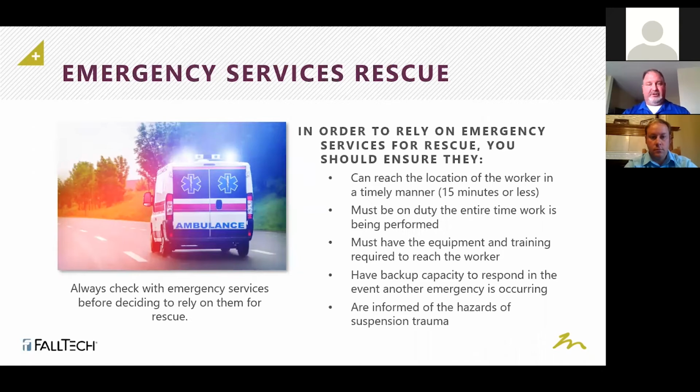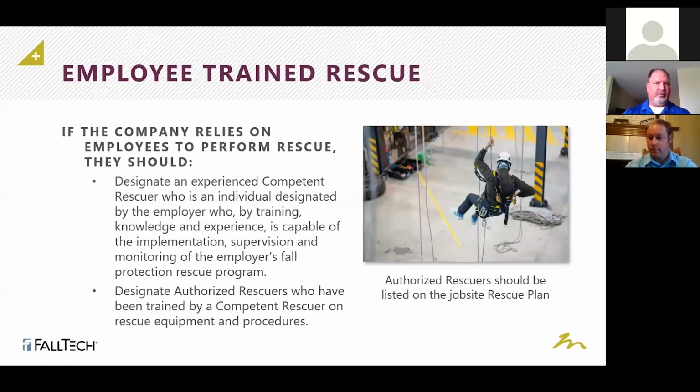If dialing 911 is your answer, you need to reach out to the closest fire department to make sure that they're aware of how to do the training. Even for fall protection or confined space, a lot of fire departments aren't prepared for it, and it's still going to take time for them to get there. If they can't be there in 15 minutes, that's not a good thing. So having your own self-rescue team ready to rescue somebody is very, very important, and making sure you have the right equipment to do the rescue.